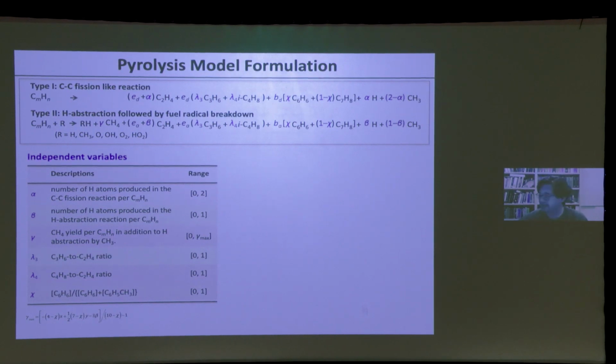If all what I said is true, and you believe what I say, then we just needed to develop some very simplified reaction models. Taking the fuel called CmHn, this can be a jet fuel, this can be a gasoline fuel. And all you have to do is conserve mass, carbon and hydrogen mass. And you can massage the lumped reaction process into something that looks like what I'm showing here.